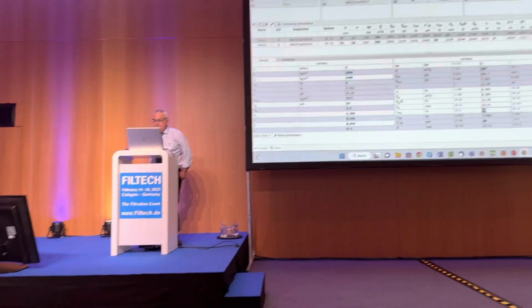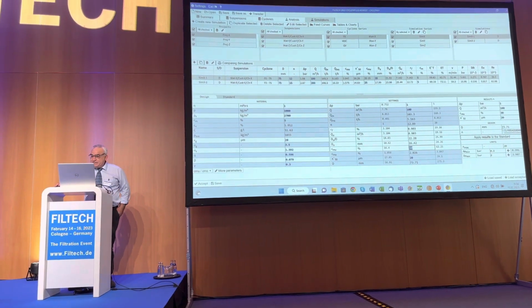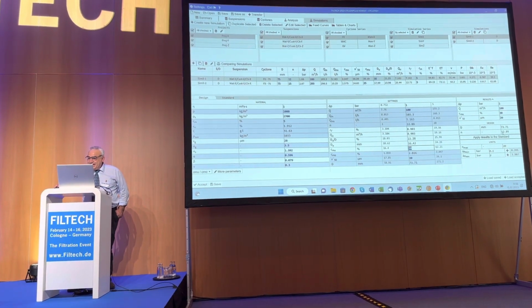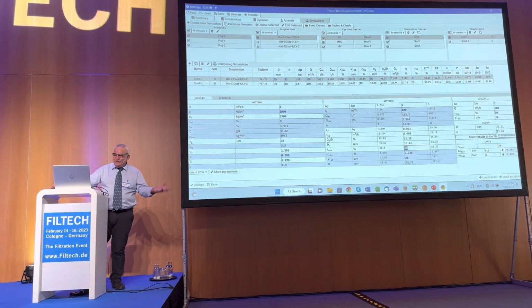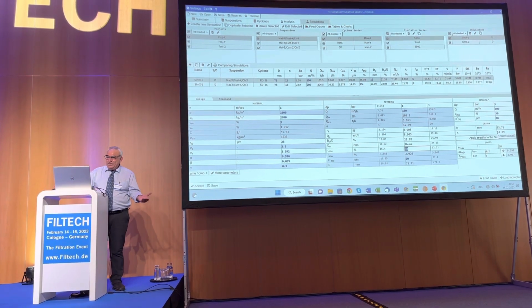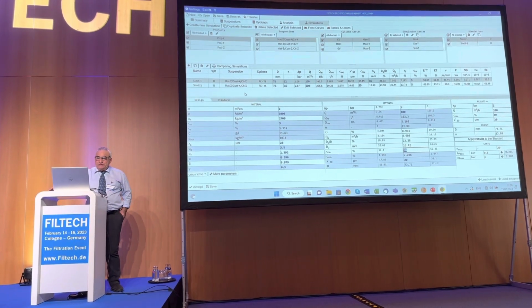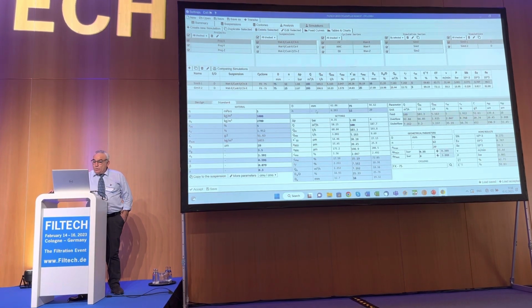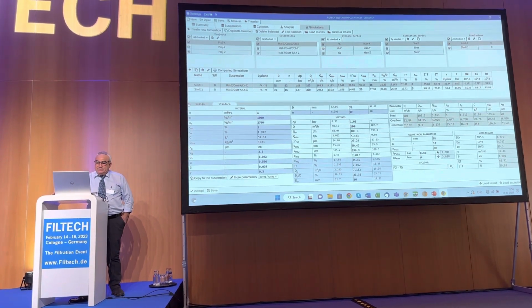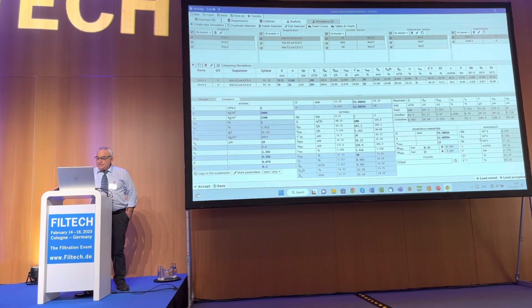We need a diameter, that is the theoretical design, the first design step, 73 millimeters, and 12.89 number of cyclones in parallel connection, yeah? And then we go to the second design step, where I apply the results to the standard.